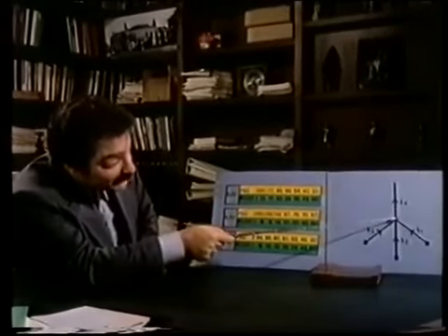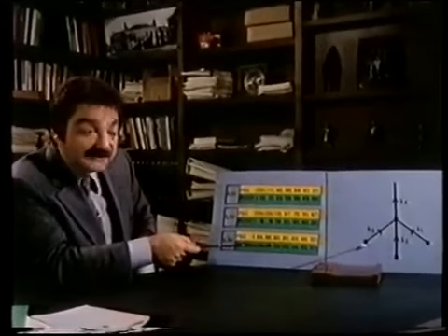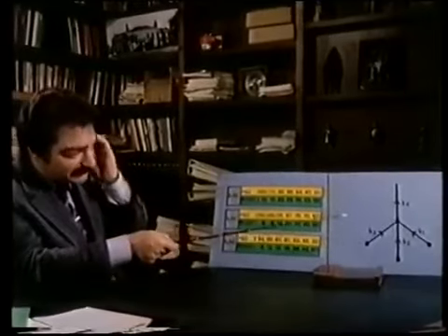The pressure at this point is the same for that pipe, or that pipe. And clearly, since my problem has a maximum pressure constraint, the pipe which has the maximum pressure square difference across it will be the one which is on a critical path. Critical path meaning that's the one which has the greatest pressure drop across the entire path.